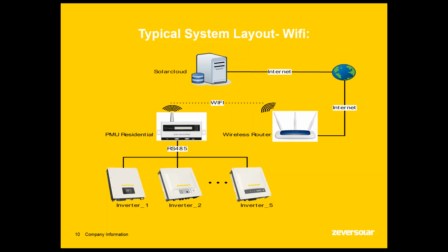The ZeverCom unit, once connected, will emit a network signal, which you'll need to connect to the customer's Wi-Fi network, which we'll go into more detail shortly. The internet will then connect to the Solar Cloud, which will update the information on the customer's Solar Cloud account.